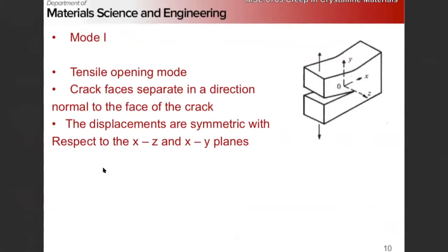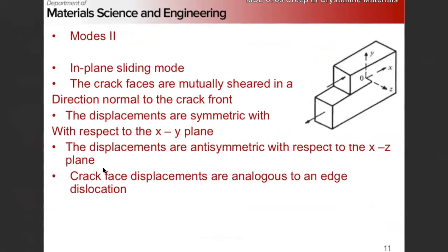of displacements. Mode 2 cracks, this in-plane sliding mode, right? The crack faces are mutually sheared in a direction orthogonal to the crack front. The crack front is here, and we're shearing perpendicular to it. The displacements are symmetric with respect to the XY plane, and they're anti-symmetric with respect to the XZ plane.